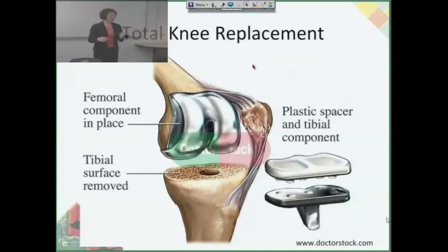And so you can already see that there's a lot of different forces that are acting on a metal like this. The biggest one that I see immediately is that you have interaction with the bone. It needs to interface really well with the bone in order to have appropriate load transfer. You have extremely high compressive forces in a joint like the knee. It can withstand up to 10 times body weight. And you also have considerable friction and wear that comes in an articulating joint like this. So it's really important to understand how these materials actually behave in all of those scenarios.